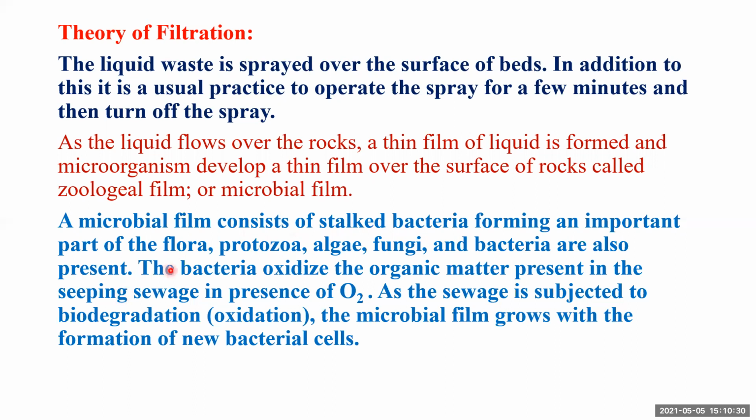What do the bacteria do? The bacteria present in the film oxidize the organic matter present in the seeping sewage. So our practice is we spray the sewage and stop. Let the liquid layer form, let the microbial layer form. You allow your bed of rocks or trickling filter to get mature, to get ripened. Then the spray of liquid waste is done at regular intervals.